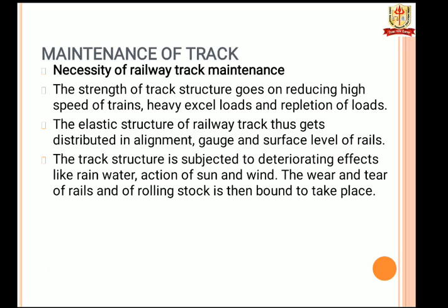Necessity of railway track maintenance. Due to the constant movement of heavy and high speed trains, the packing under the sleepers becomes loose and track geometry gets disturbed. The gauge, alignment, longitudinal as well as the cross level of the track thus get affected adversely and the safety of the track is compromised.